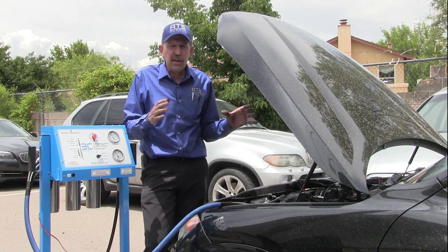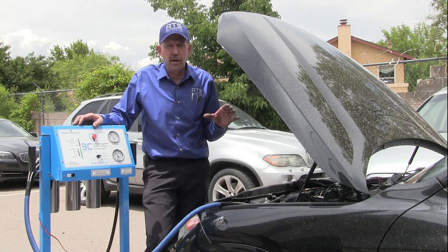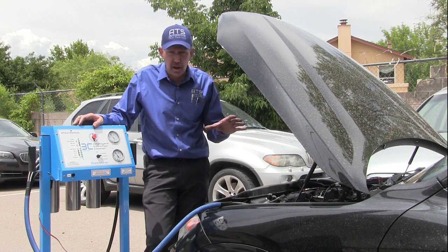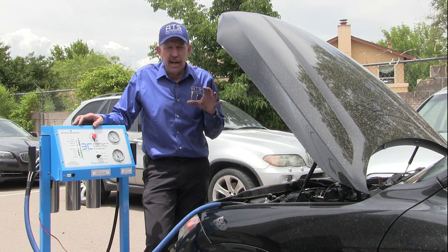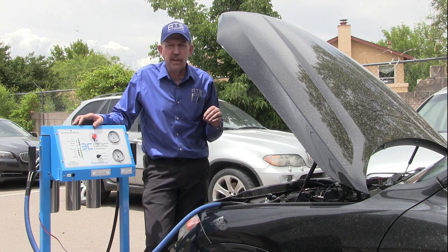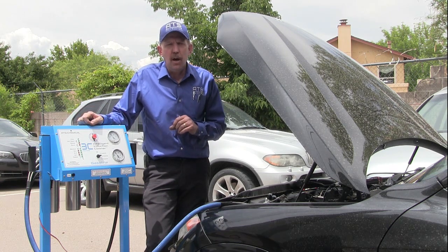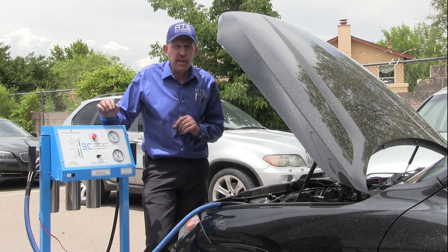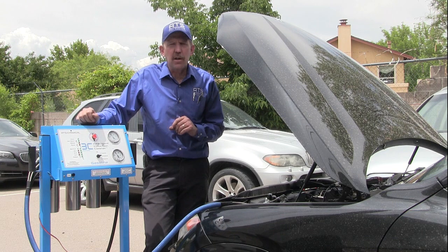At the end of the cleaning process, the 3C Intelligent Induction Cleaner is going to put on an audible alarm, and it will be on solidly. You'll know that this is done. Basically, an 8-cylinder engine is 10 minutes, a 6-cylinder engine is 12 minutes, and a 4-cylinder engine is going to be about 14 minutes. Once the alarm is going off, go ahead and get out of the car and kill the machine by hitting the emergency stop switch.